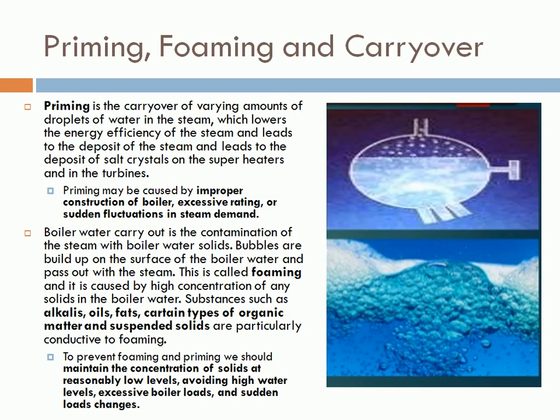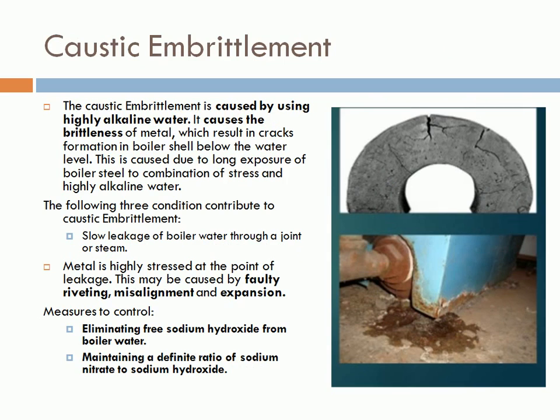So we can see that in the steam delivery, it may be caused by impurities in the water which foam up as it boils, or simply too high a water level, and it is very harmful to the valves and pistons as the lubrication is washed away. It can be dangerous as any water collecting in the cylinders is not compressible and may fracture the cylinder head or piston. So these are the effects of impurities in the form of priming, foaming and carryover.